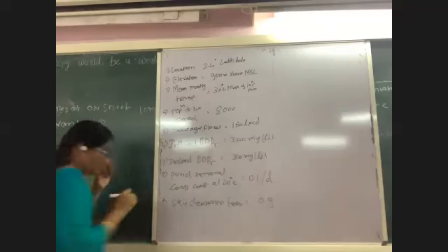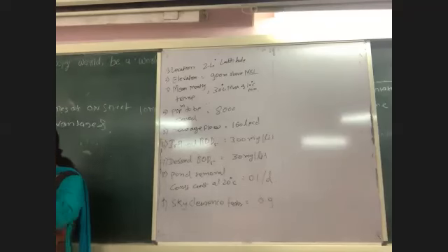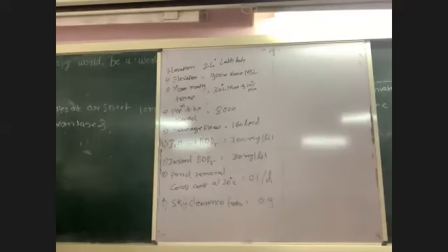Hope so. Okay. I think you might have read that problem. Now you are asked to design the oxidation pond. So first of all, what we need to calculate? First of all, you need to calculate the total BOD per capita. Population is given to you.